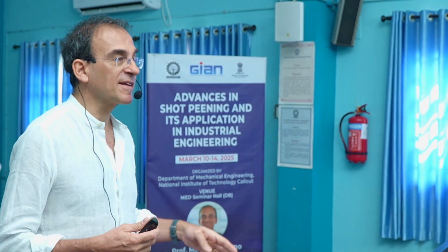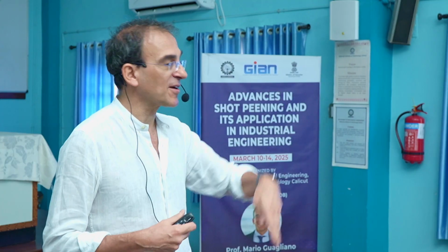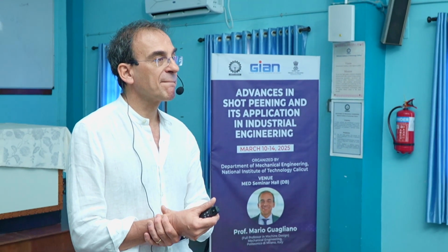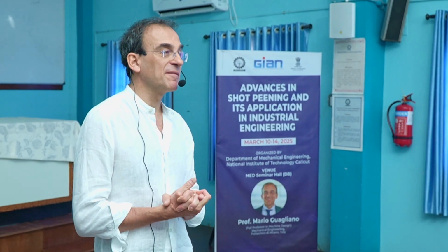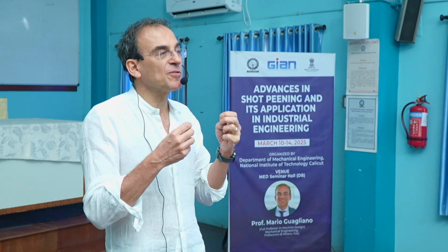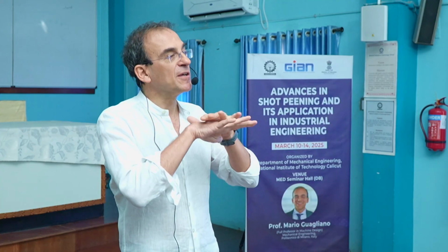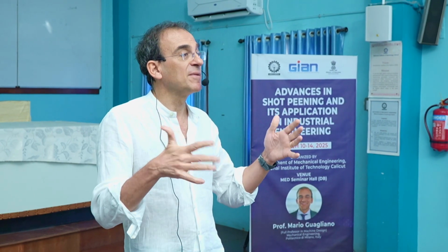Ascending and descending means that we are increasing, the gradient is positive or negative, and we are going up and then down. So that gradient effect is solely limited to the applied Almen intensity. The gradient refers to the pressure time variation. And the final effect we want by means of this new way to apply shot peening is to improve the surface quality, maintaining it for a longer time, and so maintaining grain refinement.